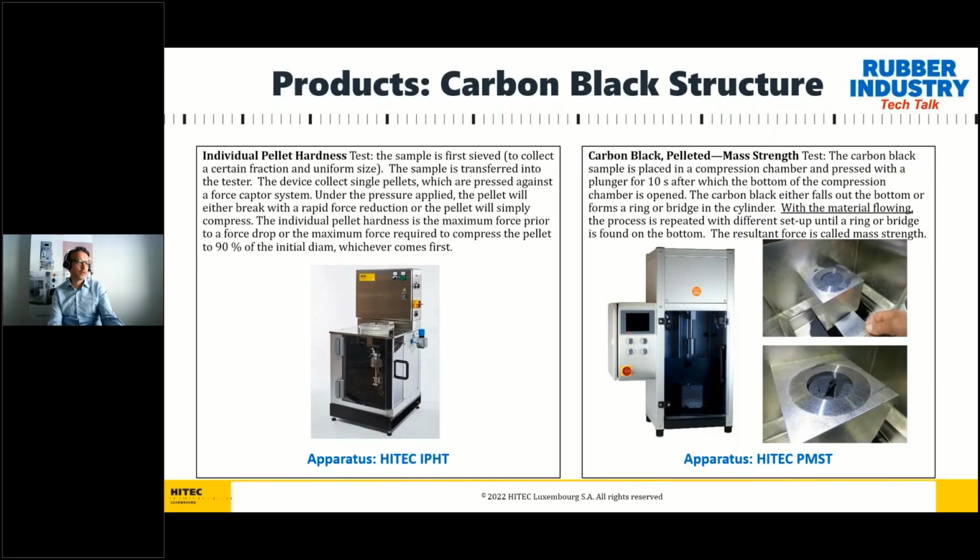The output data of this equipment are the pellet hardness and the pellet diameter. And of course, you will also have statistics about the pellet characteristics. Normally, the standard is an average of 50 pellets or an average of 20 pellets. So you will get as an output the average, the hardest 10%, 3 or 5 pellets, and the softest pellet, and you also get the individual data for each single pellet measured. This is what you get in the test report of each measurement.